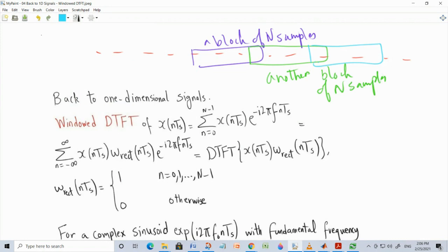This is an assumption called quasi-stationarity. For example, if you analyze a speech signal, the frequency content over 10 milliseconds is sort of stable, so you can do a Fourier transform, but you should base it on a duration of 10 milliseconds, because after that you have a new signal with new properties, and so on and so forth.